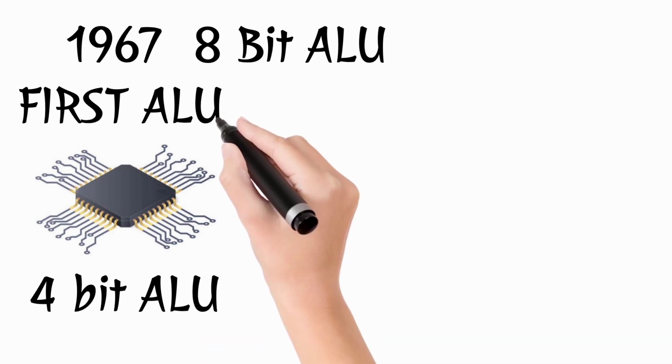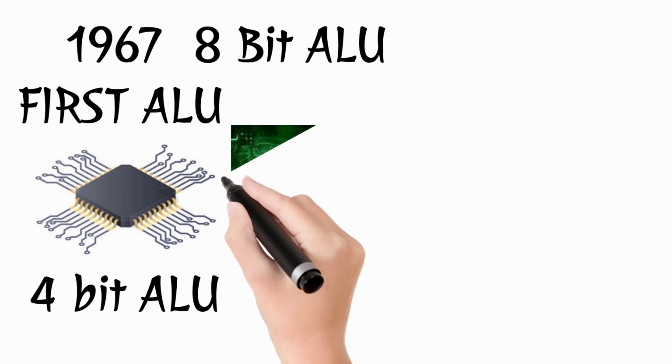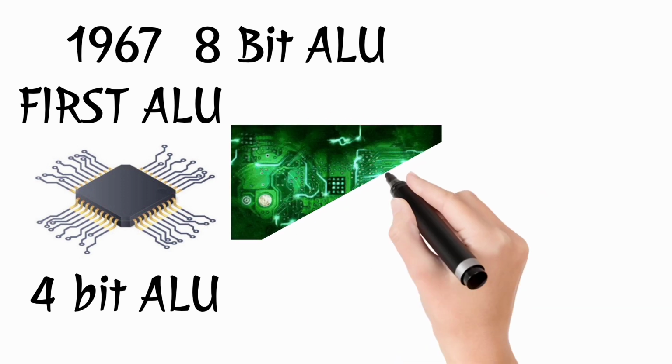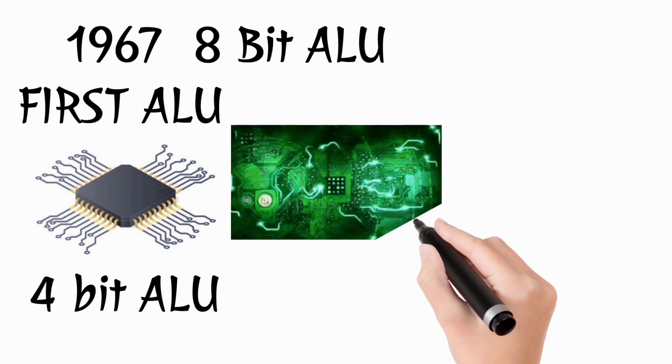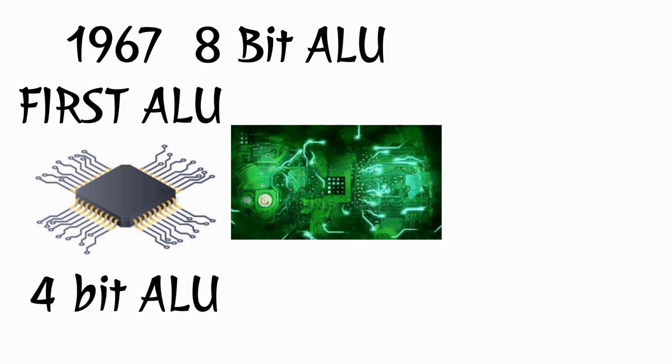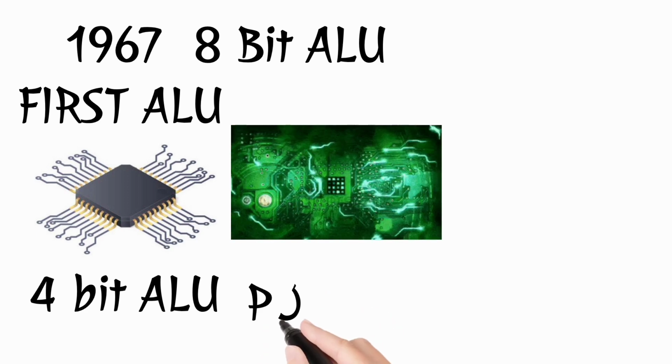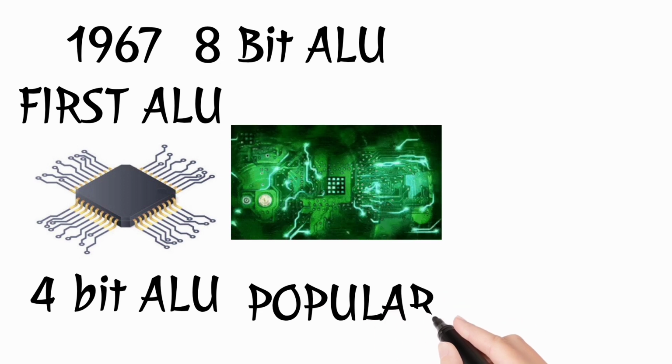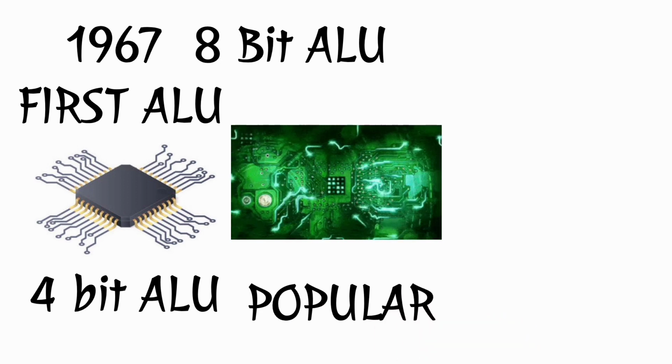These devices were typically bit-slice capable, meaning they had carry look-ahead signals that facilitated the use of multiple interconnected ALU chips to create an ALU with a wider word size. These devices quickly became popular and were widely used in bit-slice mini-computers.